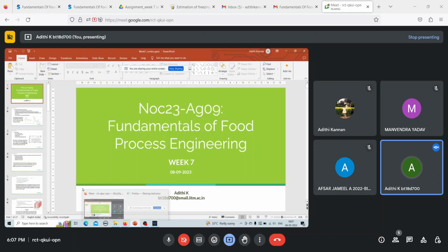We use Planck's equation when we do not have any information regarding the sensible heat being removed. Here there is no mention of what sensible heat is being removed. We don't have the specific heat capacity given for the material, so we do not know the sensible heat being removed. When no information regarding the sensible cooling has been given, there is only the freezing point directly given.